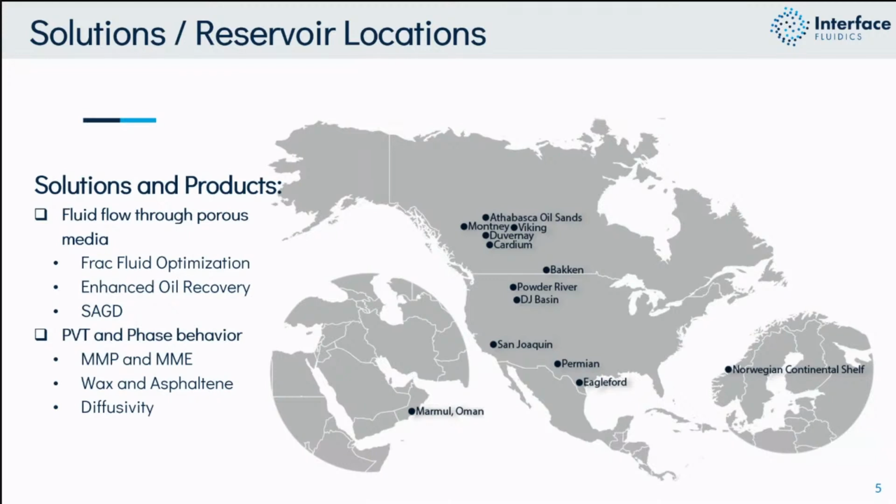Our technology allows us to measure how fluids behave in porous media by looking at frac fluid optimization, which will be the topic of today's conversation. But we also look at enhanced oil recovery, whether that's chemical, gas injection, anything else you can imagine, or SAGDs, more of a specialty in Alberta, but something we've had a long history with. Going forward, Interface also provides PVT and phase behavior data. Specifically, working on minimum miscibility pressure and MME experiments to help facilitate CO2 sequestration and gas injection, as well as measuring wax and asphaltene appearance conditions and measuring the diffusion coefficient of various fluids.